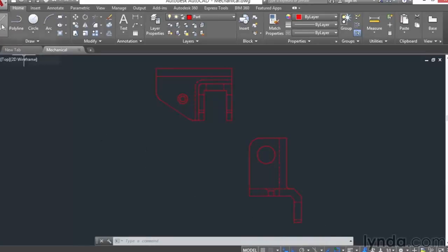And then go ahead and click the Line tool. Move the cursor over here to acquire a tracking point. The snap could say quadrant, endpoint, or intersection, but all three at this location are coincident, so it doesn't matter which one appears. However, be careful not to click, because we don't want to start drawing at this point. All we want to do is acquire the Object Snap Tracking line, which appears when you move the cursor to the left. If it doesn't appear, go back and try to reacquire it. You see, each time I do that, I either get it or I don't.